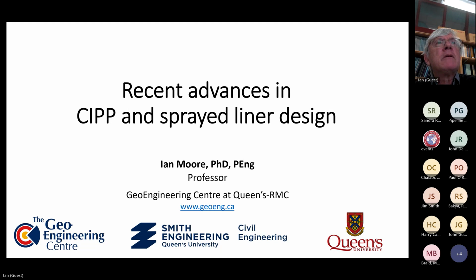So if you have heat cured, let's say felt liners, they do tend to experience shrinkage during curing. You will get a gap. And the work that I've done to date is based on the conservative condition that there's zero gap.